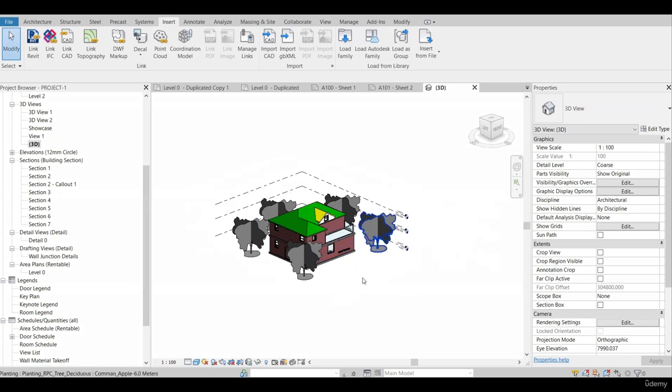As we are working in a Revit project, the extension would be .rvt. It's not necessary that every software will support the file format for import and export purposes. So there is a common format, that is IFC. By using this common format, you can export or import data between other software platforms. The .rvt file format won't be usable in other CAD software, or any relevant BIM software, and vice versa. So in order to exchange data between other software and make it compatible for data migration, we can use the IFC format.